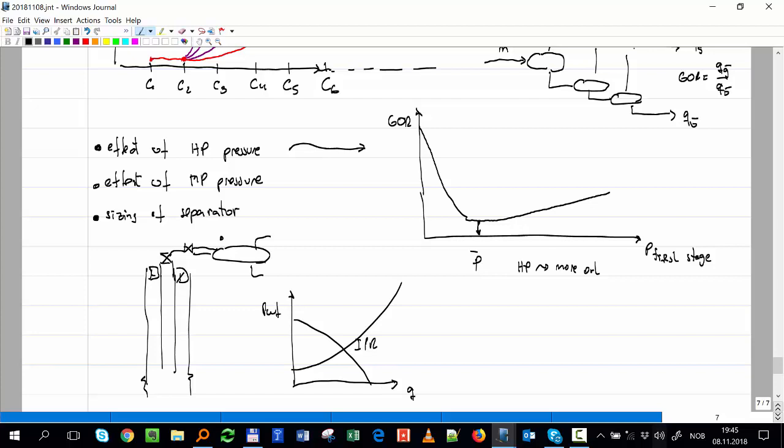Here is an exam question: what happens with the TPR when the pressure increases? It goes like this, right? Like this, for a wellhead pressure higher than this one. So even though it's something I can use to improve the GOR and get more oil, it's not something I normally like to change too much. I cannot take it very, very high because otherwise I'm reducing the rate. The mass flow that I'm getting here will be reduced.